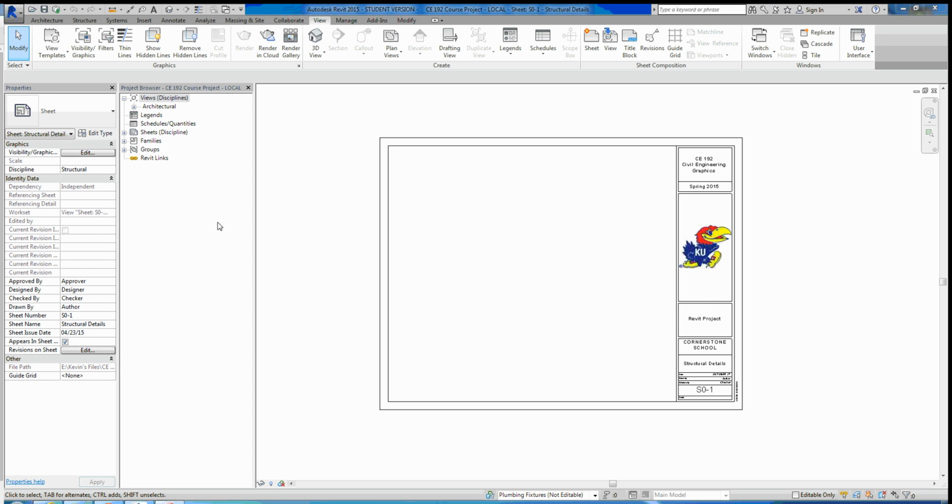is giving more an idea of the general layout and the shapes that you're going to use for your structure and all that kind of stuff, but it doesn't get as detailed as drawing connections or really in-depth details of certain things such as wall sections. So instead we'll draw two-dimensional details, and then we'll call out where these details occur on our three-dimensional project. To create a new drafting view, you'll go to the View tab up top, and you'll go to Drafting View.